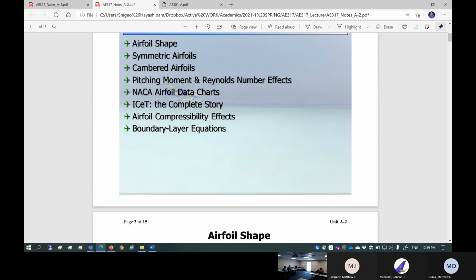And then we are going to take a look at the complete boundary layer equations, laminar or turbulent flat plate based. You're going to add that boundary layer result on top of the panel method solution, which is a combined Euler plus boundary layer solution. That is exactly what the software XFLR5 really gets.